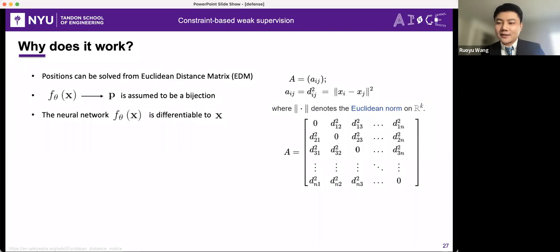So in our settings, when the robot visits a place that is very close to a place that it visited before, the output positions should be close to each other, although the position could be incorrect. And this implicitly achieves the loop closure function, which is employed by many localization approaches, although we didn't explicitly enforce the loop closure. It is automatically achieved by the property of the neural network.